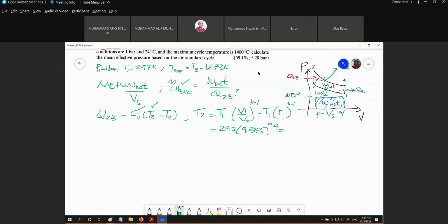Sir, what is your T2? 725.7 Kelvin. Okay, so calculate your Q23. This is 0.18 times T3, 1673 minus 725.7.